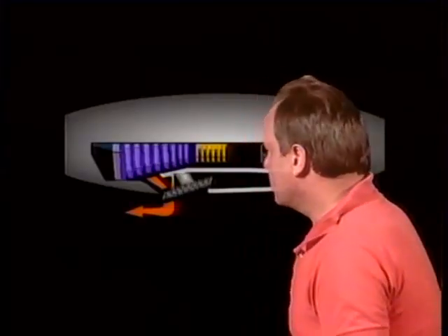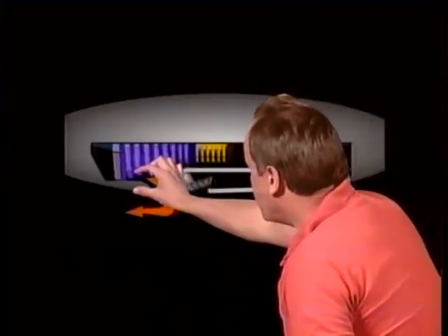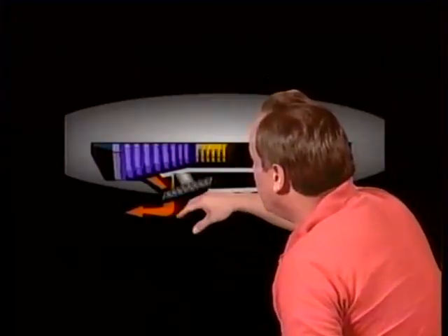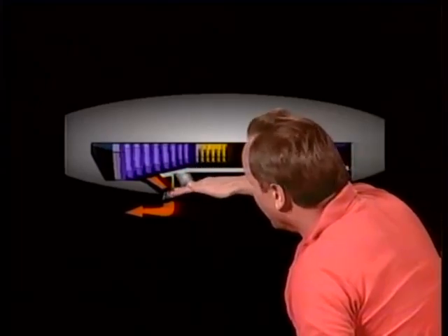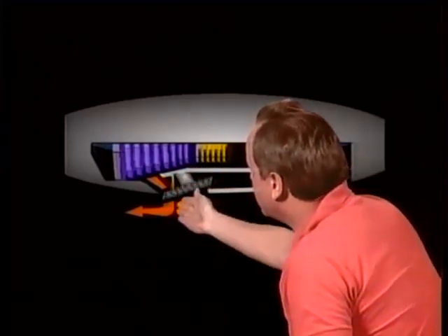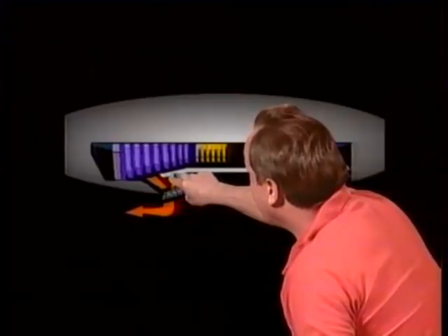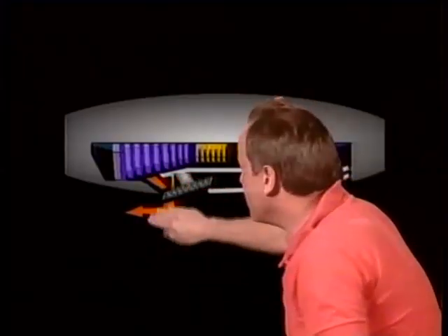Let's take a look at an aerodynamic blockage device as a thrust reverser. And this is the bypass duct on a jet engine. And when you want reverse thrust, these aerodynamic fins move down. They have a little aerodynamic shape to them. And the air comes along and hits those fins, and the aerodynamic shape bends the air and reverses the thrust. And that's an aerodynamic blockage type thrust reverser.